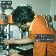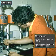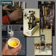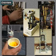The mud engineer runs tests on the drilling fluid. The mud engineer's job is to monitor and maintain the mud's properties to the specifications of the well operator. He may also recommend changes to improve drilling, such as adding more caustic soda to increase the mud's pH. In this section, we will learn about tools that are used to monitor mud properties.